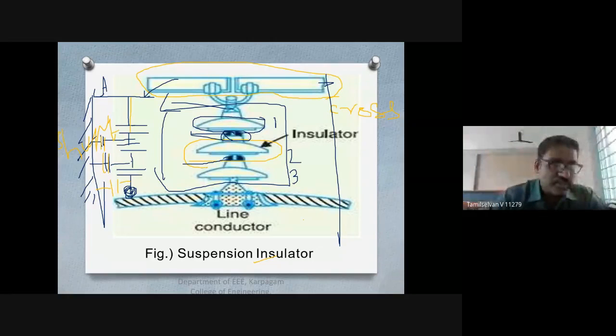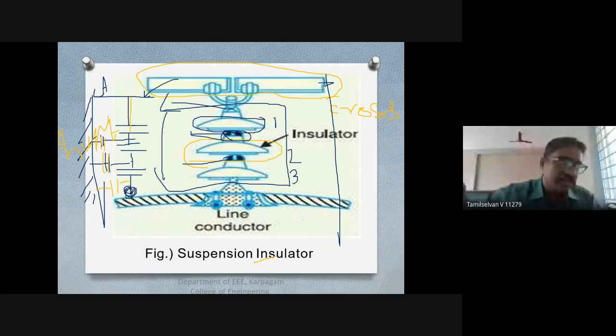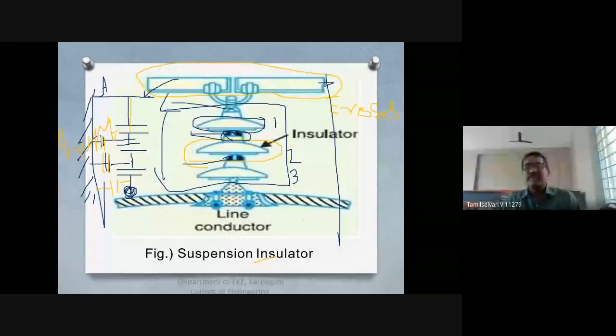In that video, after climbing, they moved the jumper away so that there would be no free discharge over the persons. Then they checked the voltage potential difference across the insulators, to see whether the insulator was damaged by flashover or puncture.